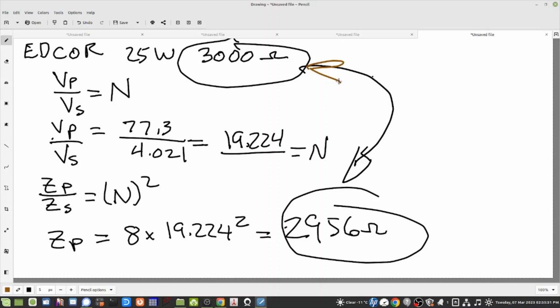So what did we learn here? Well, we learned to be a little bit suspect of our Chinese friends when we're buying their inexpensive transformers, and I will say they're inexpensive. They're the cheapest I found on AliExpress. We'll be a little bit suspect of those things, and we'll measure them for the turns ratio and impedance before we actually put them in a circuit to make sure that it's relatively close to what we want for load impedance.